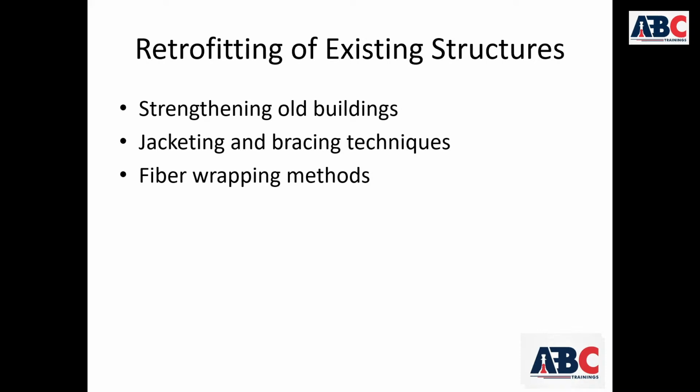Next is jacketing techniques. One of the most common retrofitting methods is jacketing. Jacketing means increasing the size and strength of the structural members. Column jacketing and beam jacketing are used here.